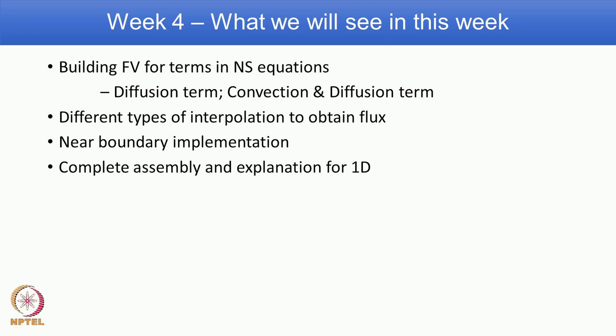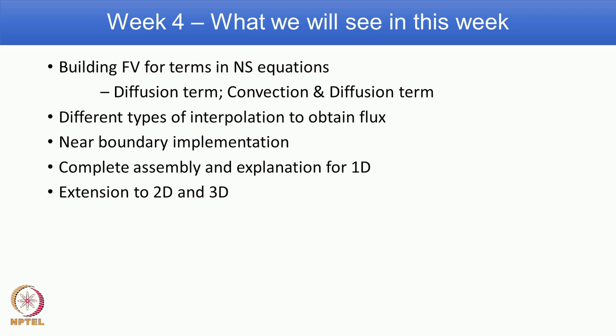There is a special treatment for near boundary implementation. Near boundary nodes will have to account for boundary conditions, and we will see how the finite volume formulation gets rewritten for near boundary accounting. This will complete in detail the finite volume formulation without the time derivative term.